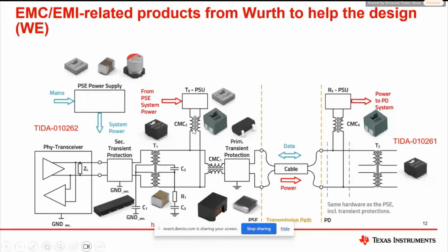You might see this is a common mode choke, but you have the two dots and you might think this is a weird connection. Well, this common mode choke is wired in this way because it prevents any differential DC current from saturating the choke, so that the signal that opposes the impedance of each choke winding is thus decoupled.